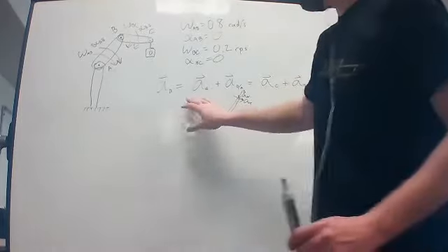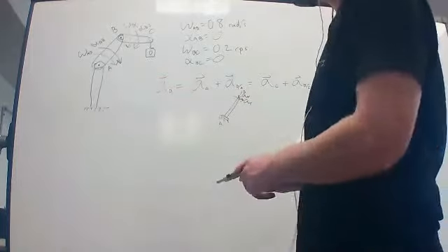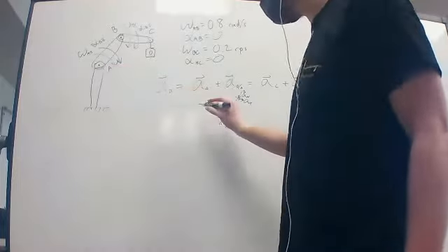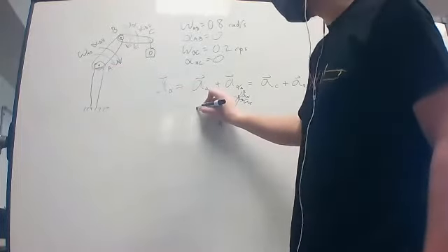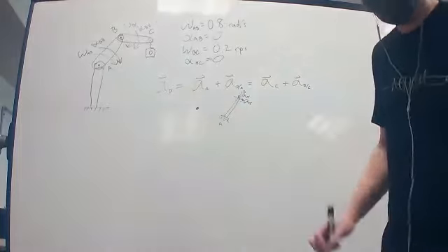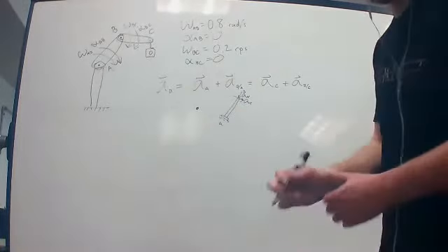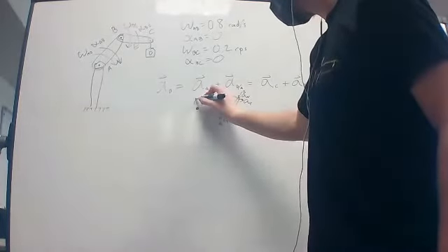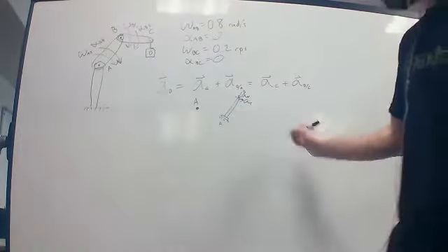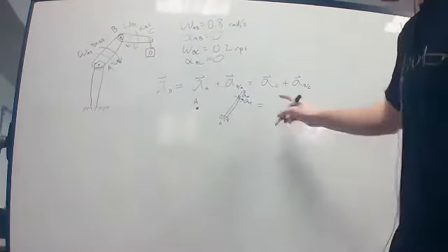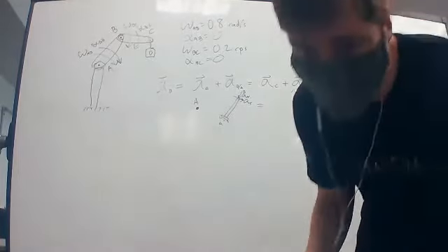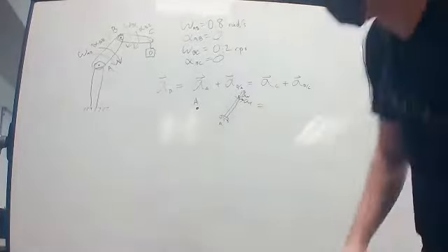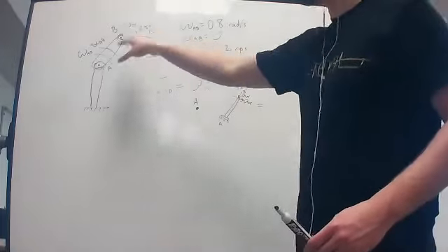So coming back to our acceleration at A, we're treating A as a fixed point because it is. This is a stiff piece that doesn't move, and so A also doesn't move. A is going to be just a fixed point constant. Where this is A. That's going to be equal to AC, which AC can be modeled as unknown acceleration because it's going to be moving on the end of a general planar motion.